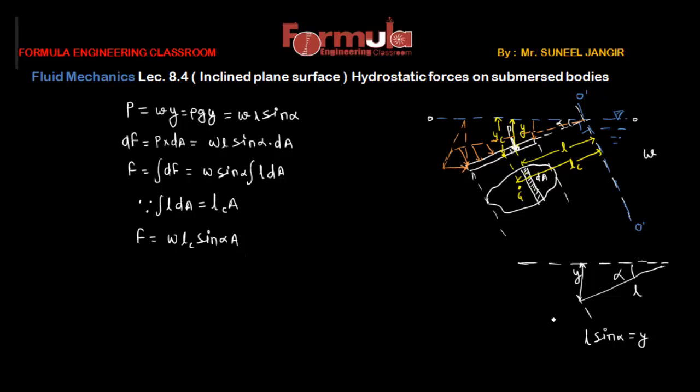Now again, we are defining Y_C as the distance of the center of gravity from the free surface, and from this imaginary surface this value is equal to L_C. So we can say that L_C sine alpha will be equal to Y_C, and we can replace this value.